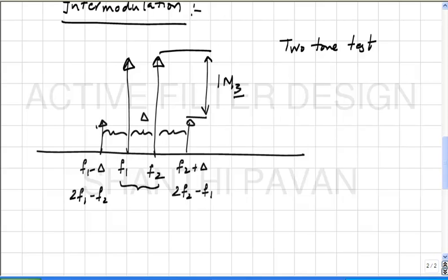As you can expect, as frequency increases, the capacitor current increases, so you would expect that this becomes less and less valid, which means that the intermodulation distortion should increase. Now, all nodes in the filter will typically have a maximum response around which frequency? Around omega naught, right?